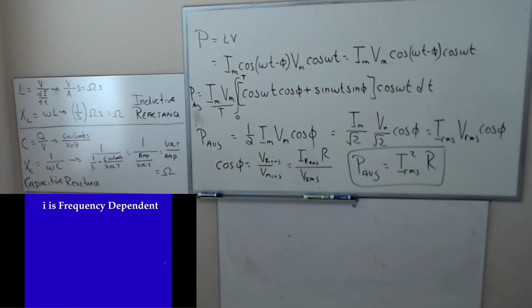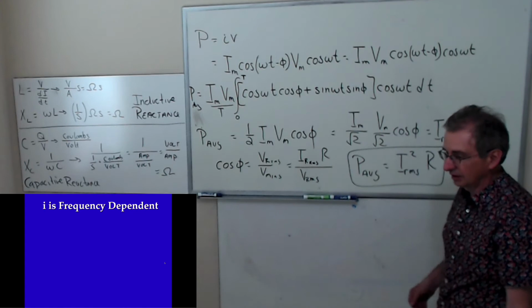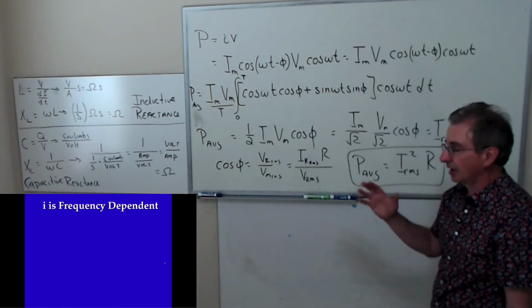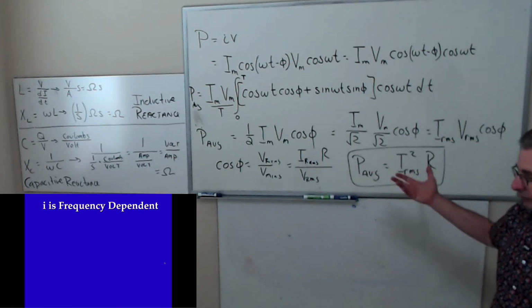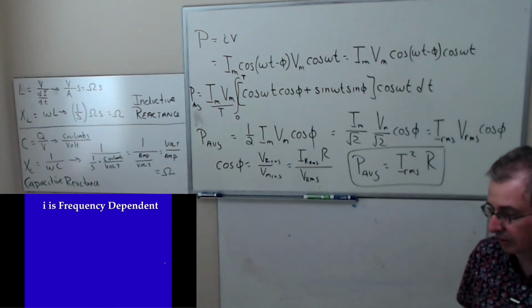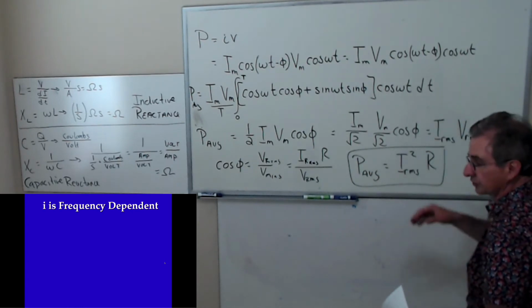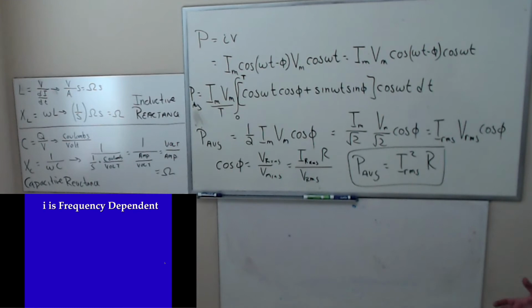And we could do that because they were in series. Yeah, we are analyzing the series version of the circuit. But in reality, if they're in parallel, you're going to see that the power loss is just due to the resistor. You're not going to get any power loss due to the capacitor and inductor, even if you got a parallel circuit. This expression would look different for a different circuit. But in the end, you'll see that the average power loss in the cycle is all due to the resistance.